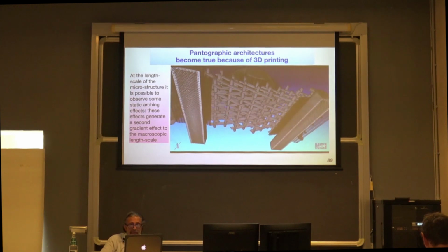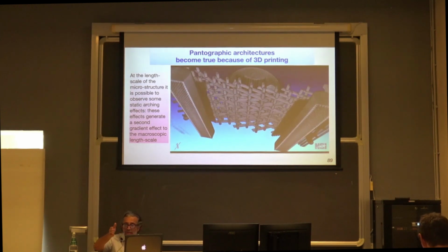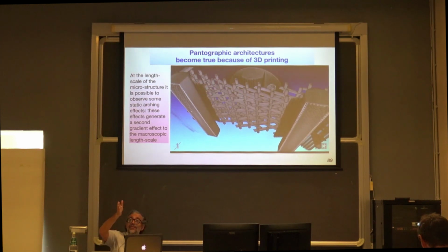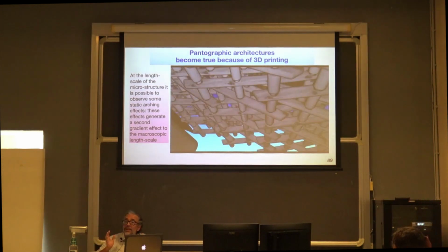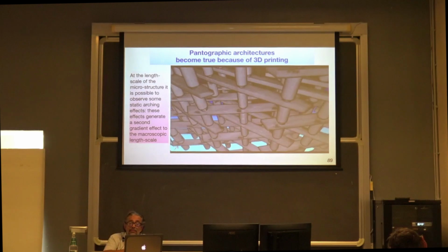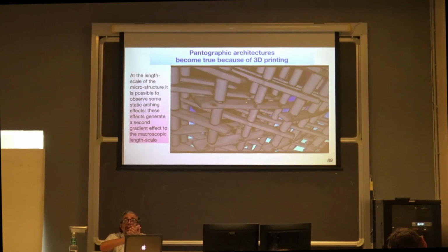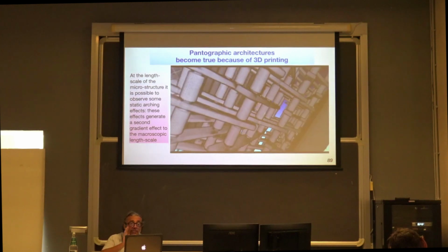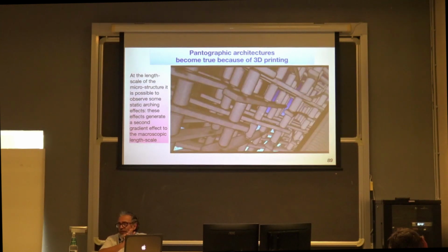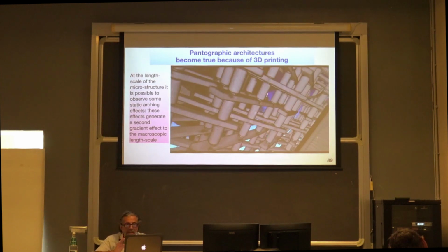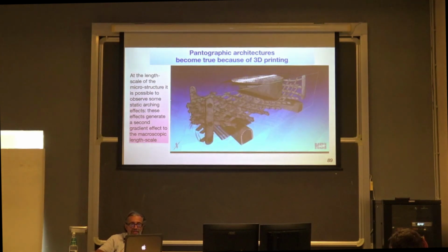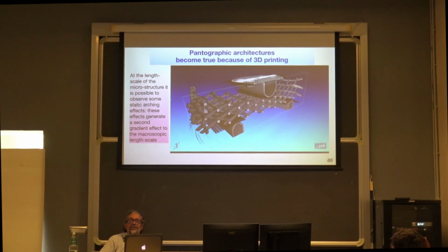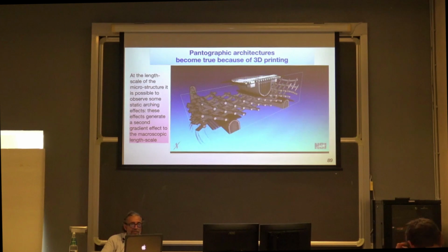And if it goes away, you will see now what happens. We can have Cauchy cuts. You can remove a part of the specimen, and you have the remaining part of the specimen, and you can check what happens at the surface. So you can measure the deformation, not contact forces. You can measure the deformation in the cut surface. Look, this is now the Cauchy cut, which you can get for studying what happens in the interior of your continuum. Okay,